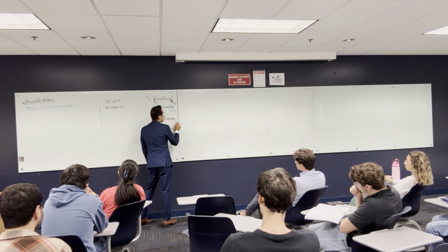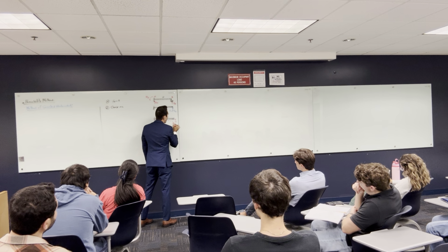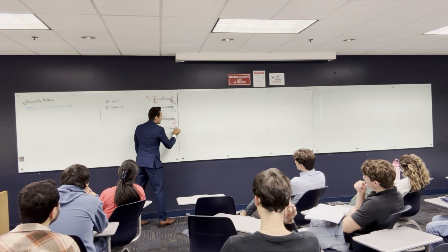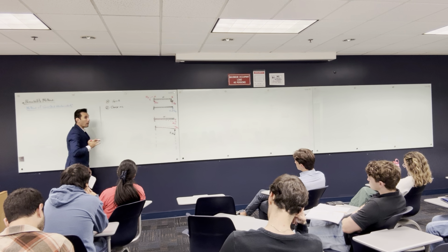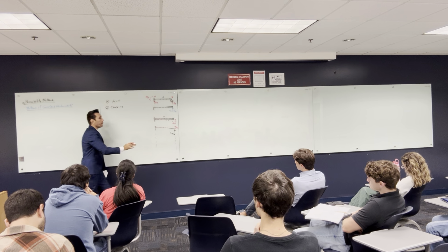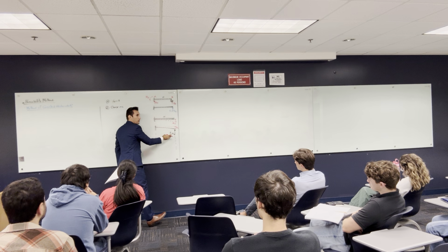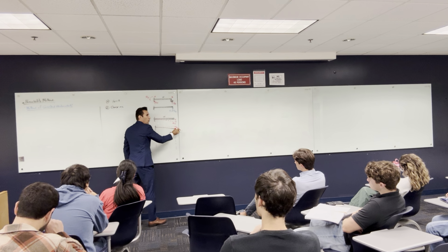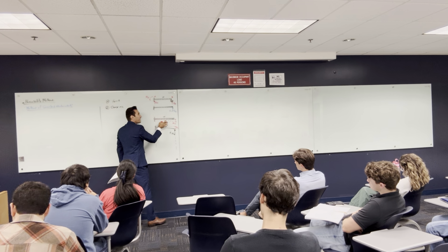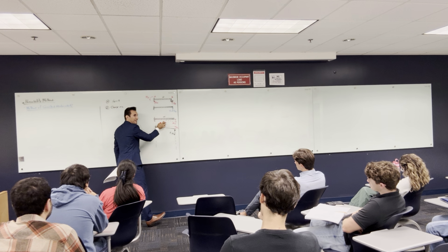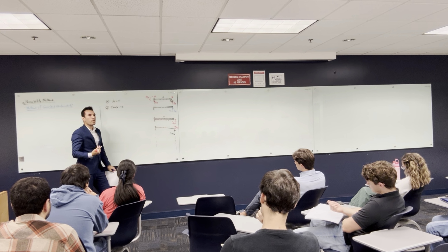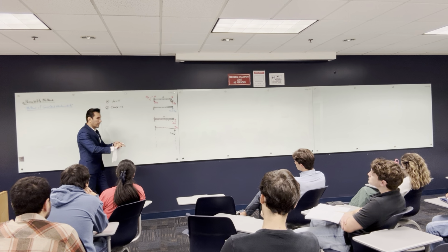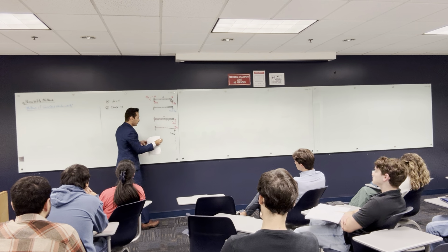We call this delta, we call it delta 1, 1. All right? So our mission is to find the value of F force that is going to make a delta 1 equal to the delta 1 that comes from the original system, or the main system, or the determinate system, okay? But the thing is, we made it much easier. What if we take this system, this one,